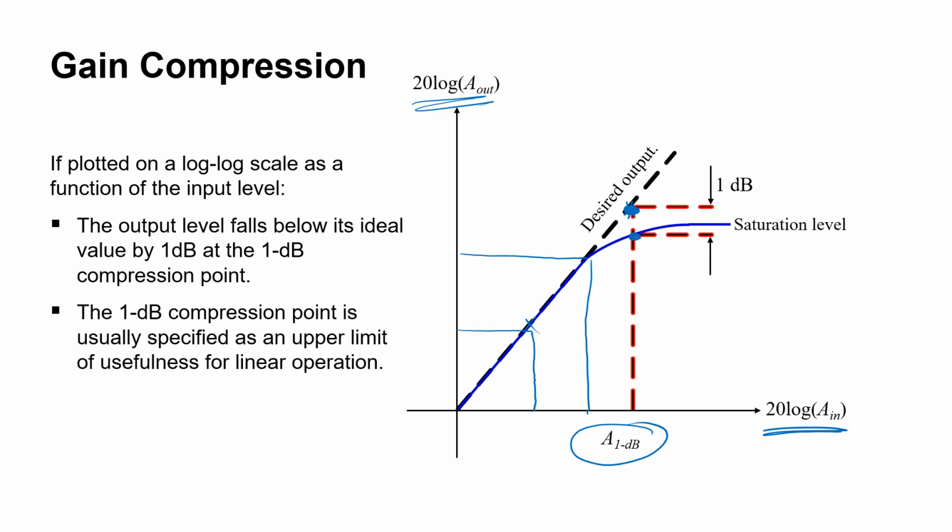So I am taking a low noise amplifier, LNA, and if I test that my LNA has a 1 dB compression point at an input level of, say, 10 dB, then I would define all my power levels of my device based upon this 10 dB maximum threshold, because I know that if I increase the input power of my receiver or my transmitter more than this 10 dB value, then my amplifier will enter into a non-linear realm